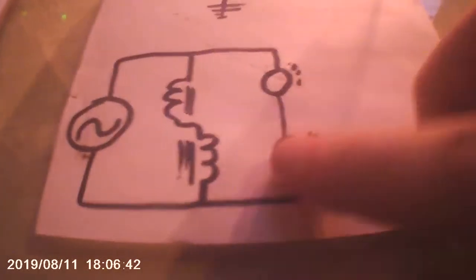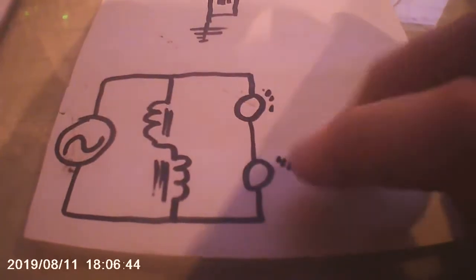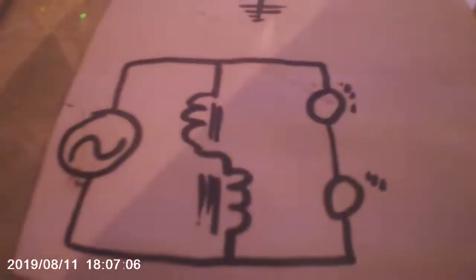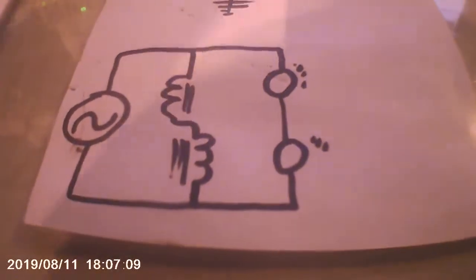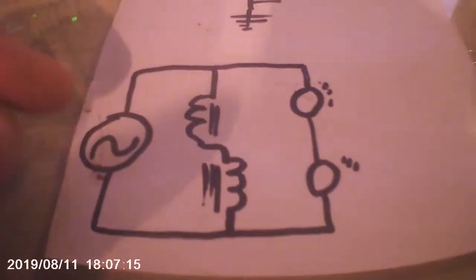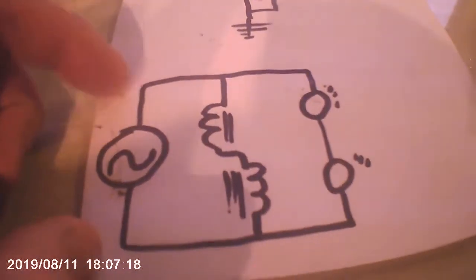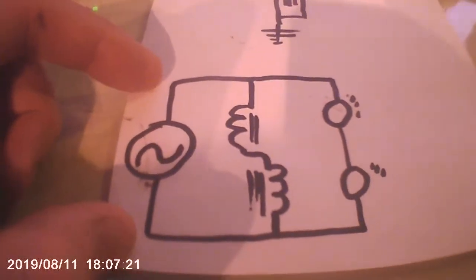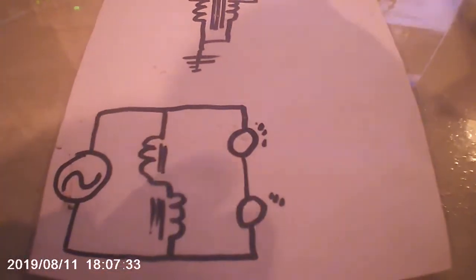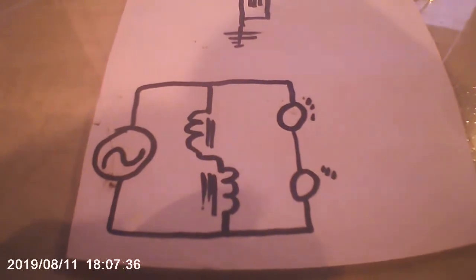However, I was pretty sure that this circuit should work with high frequency ferrite cores, such as that and many others. However, my frequency sweep does seem to be fine for some ferrites. However, because it's only going to about 15 kilohertz, it's entirely possible that it's not enough. The amplitude of all these cores was tapering off and hitting about 0 by the time it got to 15 kilohertz. So it might be hurting the situation, it might not be, but I'm going to proceed.